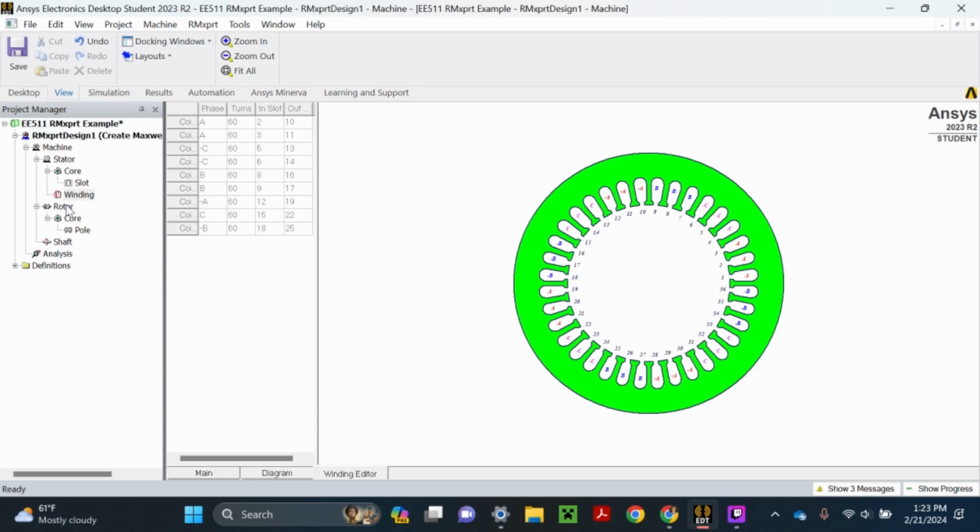Also, some people use rectangular wire because that actually helps with skin effect. And that's good because rectangular, if it's like a bar, is flexible in one dimension. So this is good actually, and they have less wasted space between the circles. So I prefer this. If you can make this wire, this is the best choice. And they're a little bit more expensive.